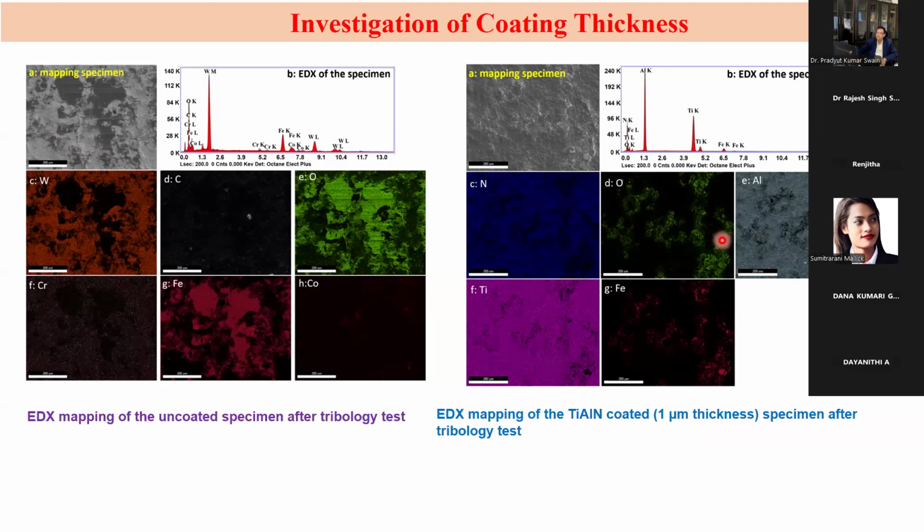The process is actually a combination of adhesion and abrasion. Adhesion means there is some chemical affinity and material transfer. And abrasion generally happens when, let's say, the hardness of one surface is less; then we generally see the surface is very nascent, that means very clean, but obviously there are some asperities.